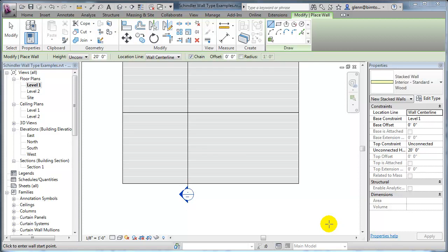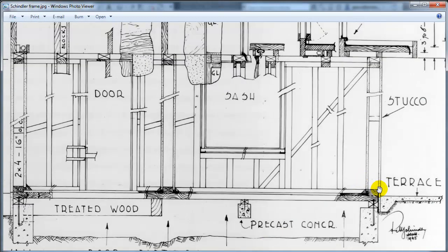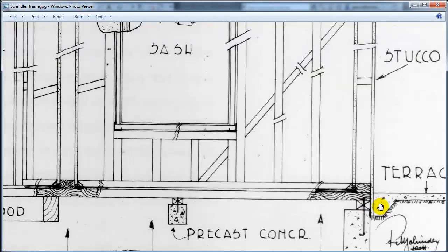And that's sort of the same case with these wall systems. So what we're going to do now, having created these wall systems, is just go through and place them. And you're going to find this is actually one of the easier parts of what we're going to do. Let's try creating some of these different details. If I go back and look at, for example, this area over here, the clerestory area, on what's for me the top of the house, we have the standard wall height, 6'10.5" tall, just kind of aligned here. Notice that as we place the wall, the stud layer is going to line up with the outside of the concrete and the outside of that subfloor, and that's going to be important as we place it. So let's start with that one. That's probably the easiest case to look at.